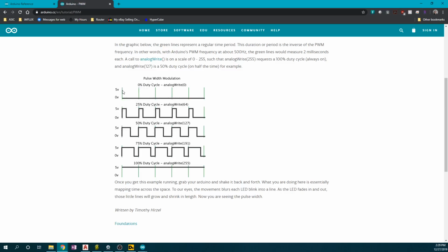In one of these cycles is our pulse width. When you send out a pulse width of 25%, you will turn on your output for 25% of that cycle. There's 490 of these in each second, and in each cycle, this width is determined by the percentage of our duty cycle. If you put in 0%, it turns the pin off. It's all the way off, there is no pulse width. As you start increasing that value, it increases the pulse width all the way up to 100%.